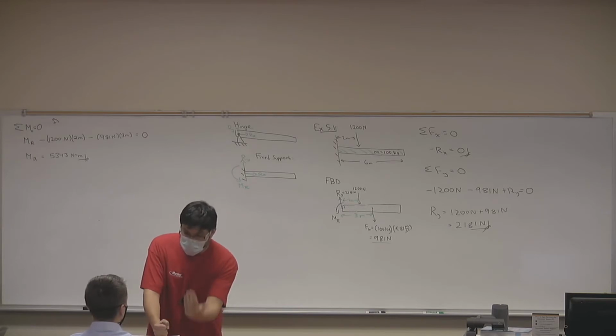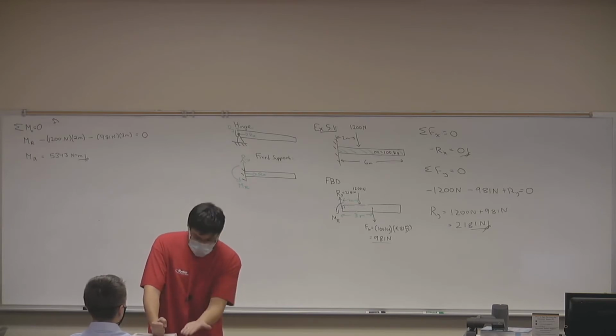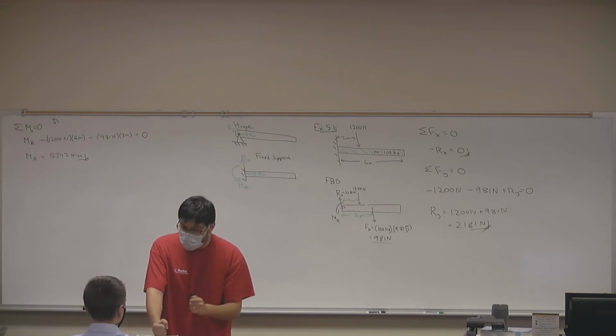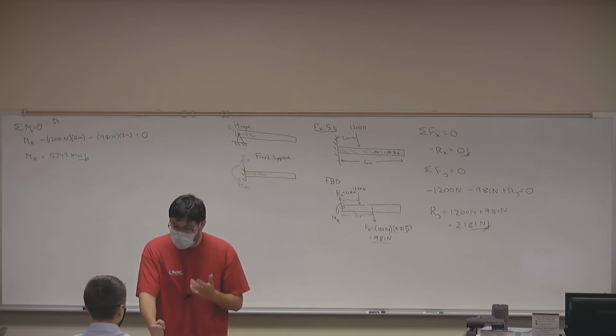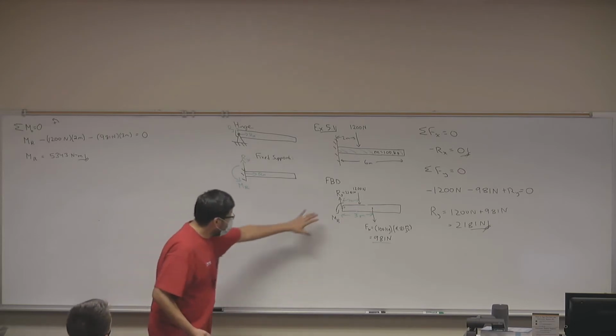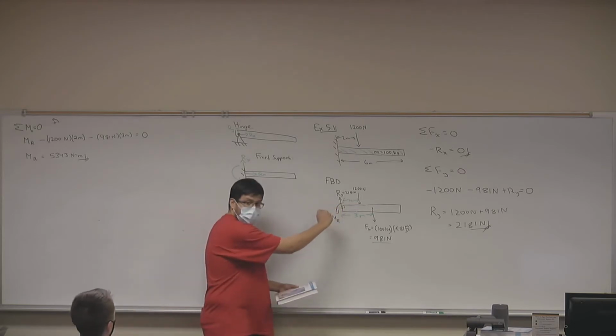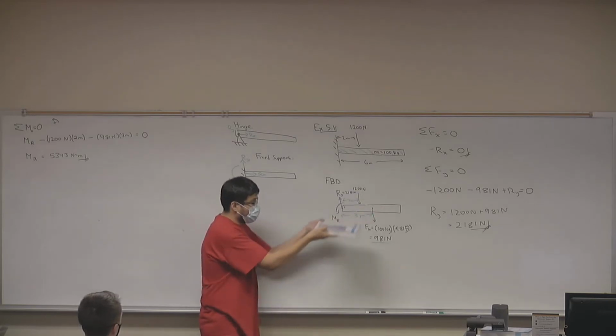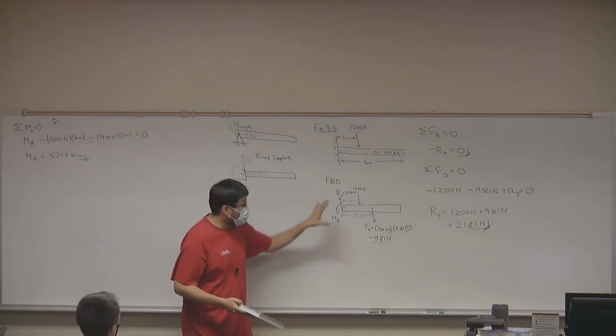You're applying a vertical force that's keeping it at its elevation. You're also, with your wrists, applying a rotation. So it doesn't matter where you apply the rotation. The fact that you're applying it means that the book is not going to rotate. So this moment is your wrists just rotating it. It has nothing to do with the force that you're applying. So it's already a moment, right?